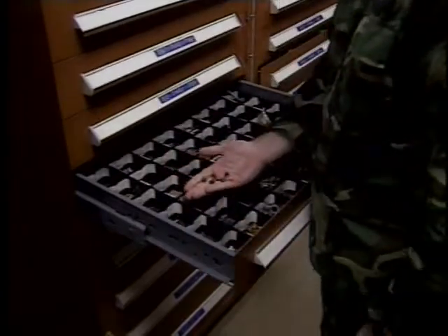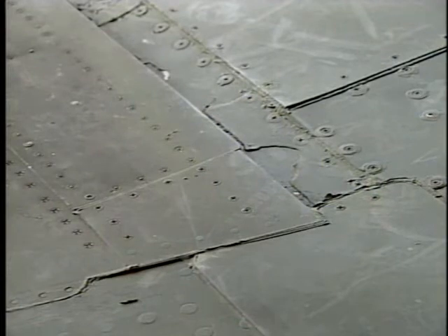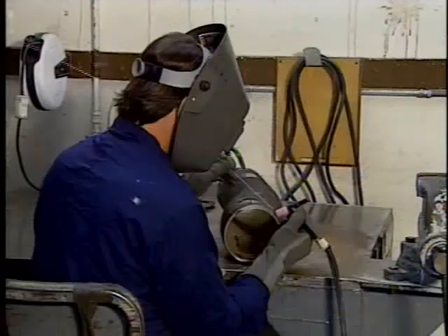We won't list all of the different aircraft and their corrosion-prone areas, but here are some general problems to be aware of. Fasteners are found in almost every area on aircraft and are often problem areas. These areas are subject to heavy operational loads, moisture intrusion, and possible corrosion from the surrounding aircraft skin.